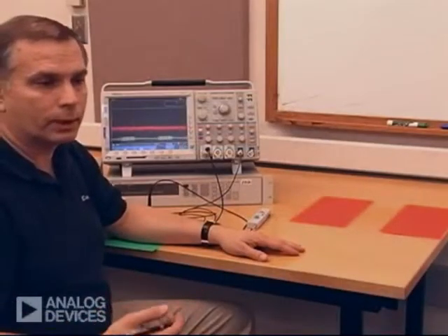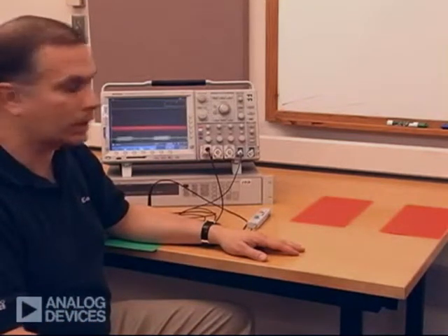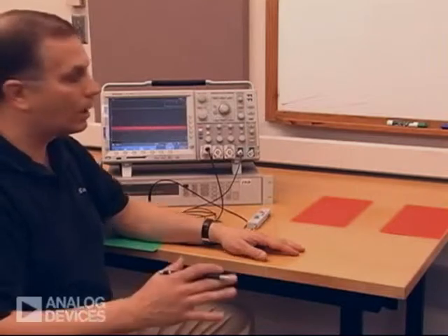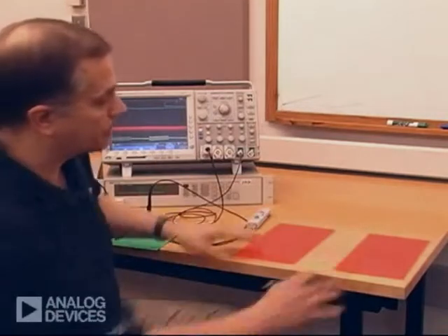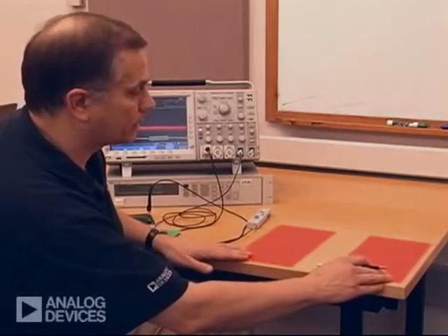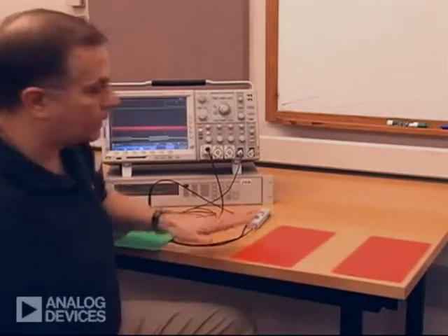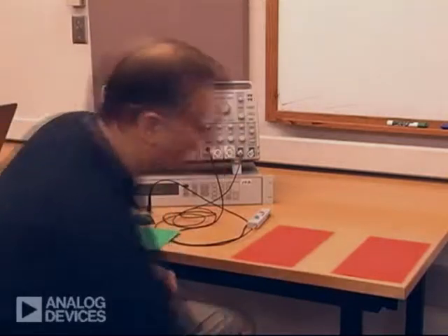In order to improve the conducted noise, in other words, the noise that's being conducted onto the VDD and power lines, we'd like to go through one circuit solution, a PC board solution that helps immensely. Let's assume that these two things represent the input and the output power plane for a standard circuit board.